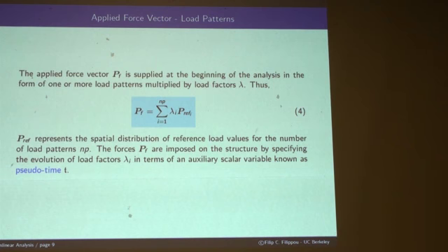The applied force vector is typically supplied at the beginning of the analysis in the form of one or more load patterns that are multiplied by individual load factors, right? So you have basically the gravity load, which is constant over time, and then you have a lateral force which may be linearly increasing with time. By the way, that time t is a pseudo time, it's not real time, right?